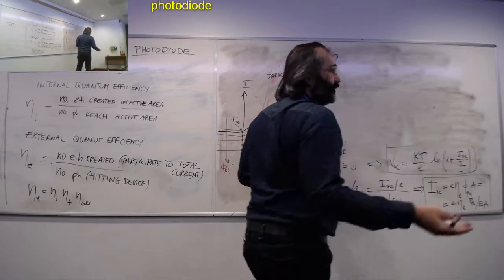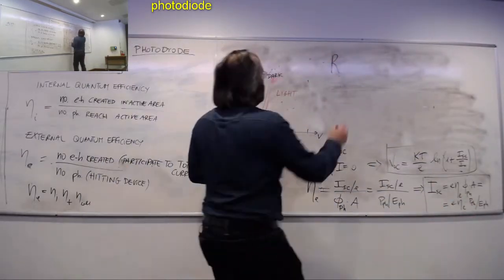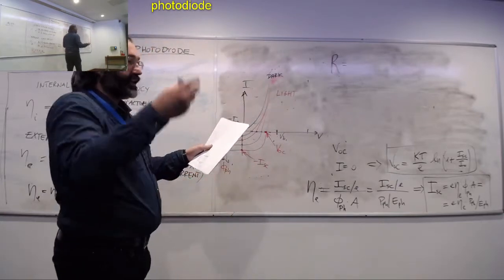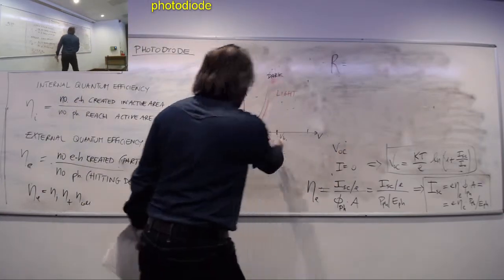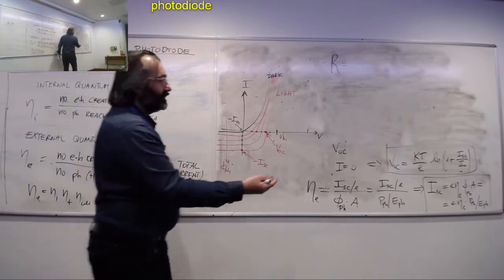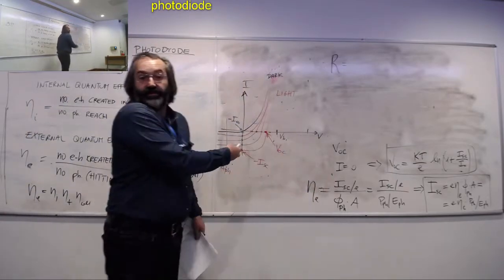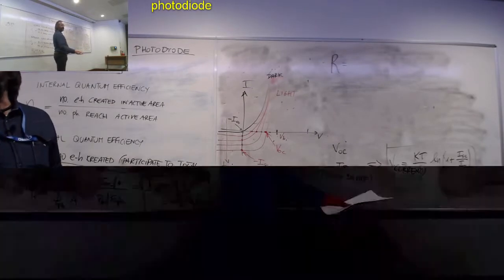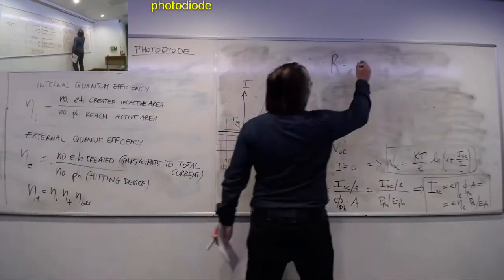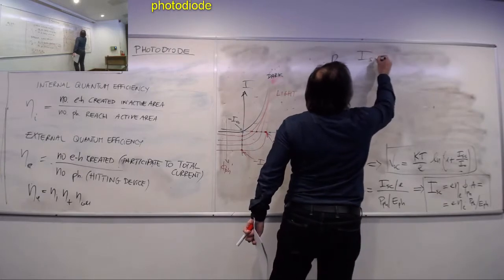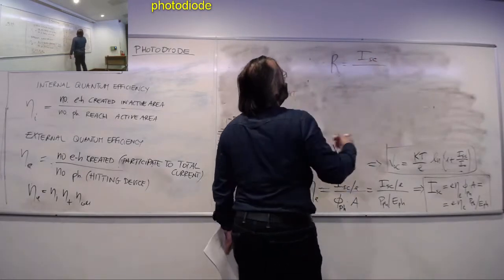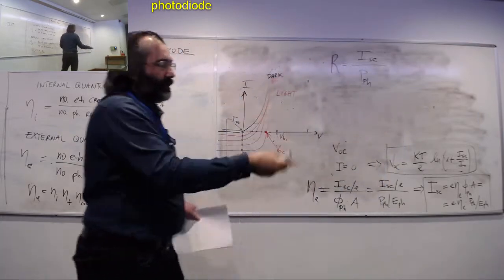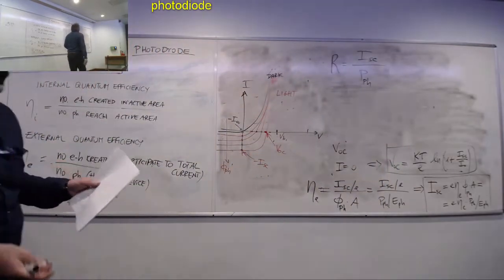generally for photodetectors is the so-called responsivity R, which is the ratio. So who is responding to light is ISC. We've demonstrated it. When light is hitting the device, some ISC is generated. So it's the ratio between the light response, ISC, divided by the power of the source, the power of the beams, of the photons that are hitting the device.